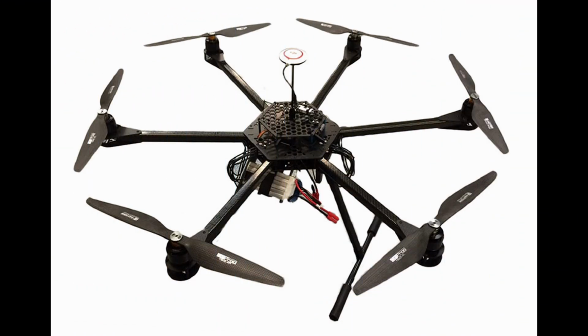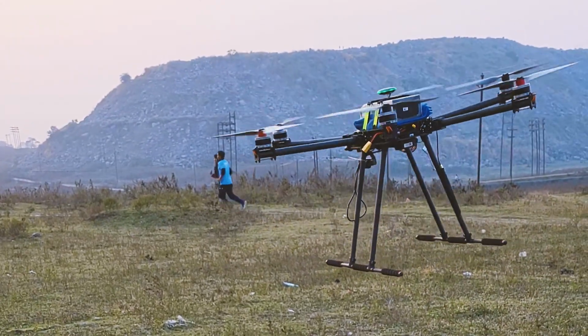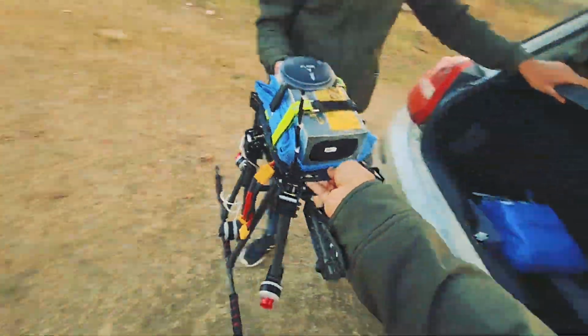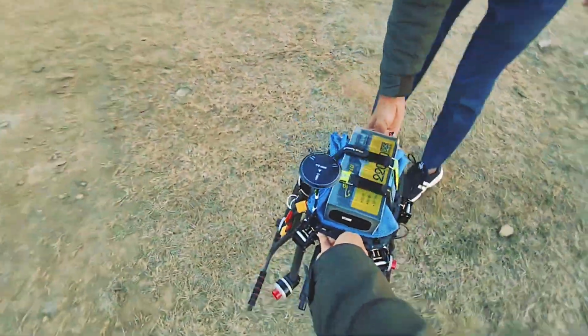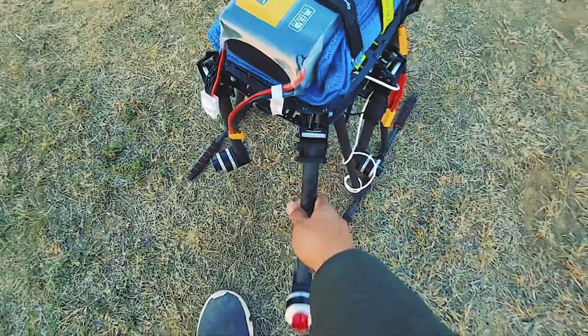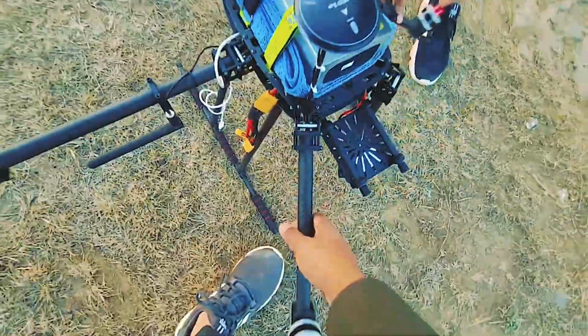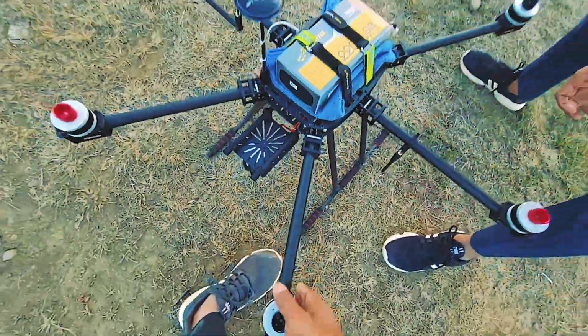Now, what if we just add more rotors? That's the basic idea behind hexacopters and octocopters. More thrust, more redundancy, more stability. A hexacopter has 6 motors arranged in a hexagonal pattern. That means 3 pairs of counter-rotating motors. Same control principle as a quadcopter, but more power. You can generate more total thrust with the same size rotors, or use smaller rotors and generate the same thrust more efficiently.